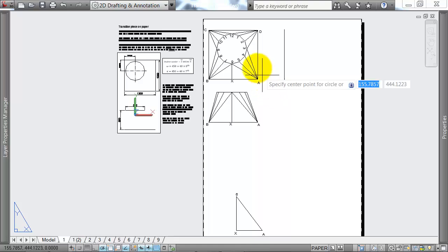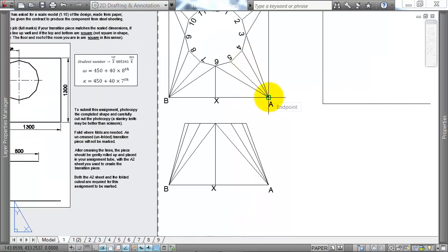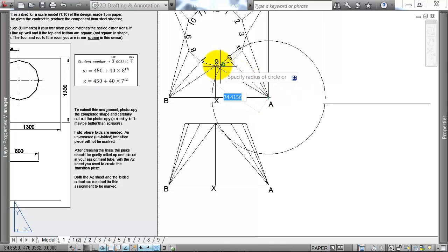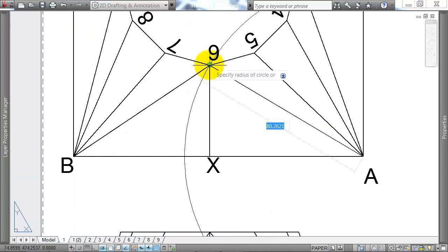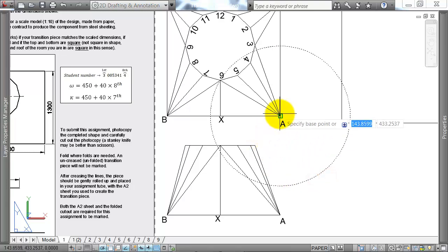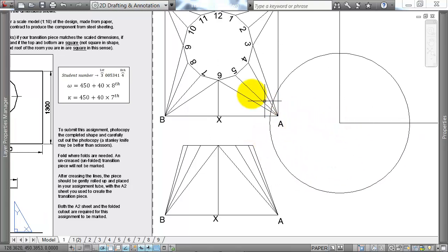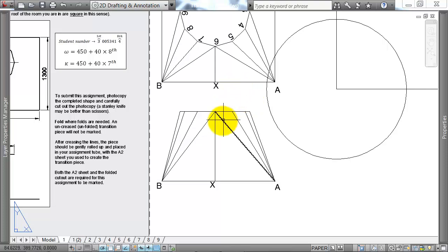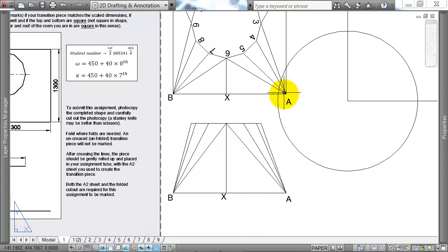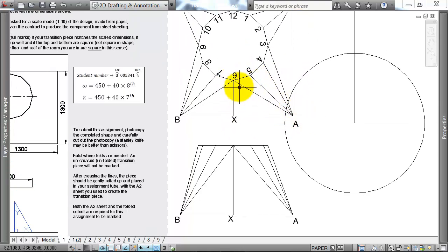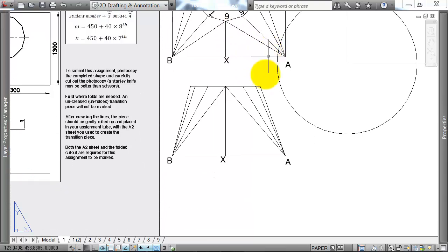We can double check that answer though, just make sure that that's actually what's going on. So if I check the length of A6 in this top view, and I'll copy this over to my point there, and then I need to get one of the dimension values from here. Now in the top view, this circle that I just created, that was measuring the x direction and the y direction, let's say the width and the depth of line A6, because in the top down view we can already see width and depth. What we can't see in the top down view is height.